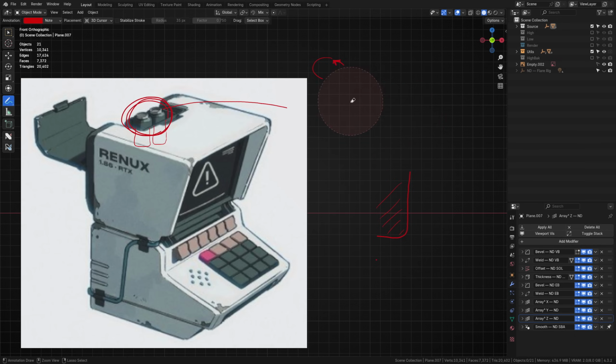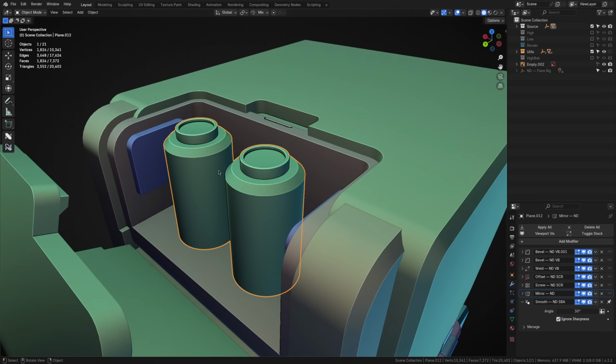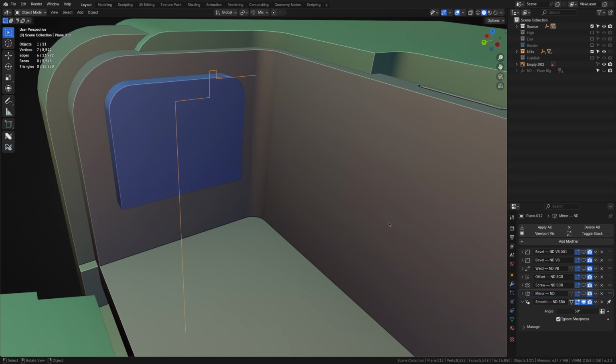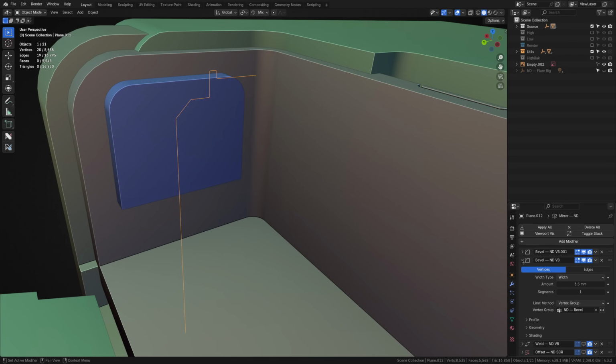Let's go over and take a look. I'll turn off all the modifiers. Here's the base sketch I went with. Now, I also used a couple of vertex bevels to curve the piece that sticks up at the top. I then also added a chamfer to this outside corner. I added it as a chamfer and not directly to the sketch because this allows me to adjust this detail later by tweaking the values in the modifier stack without having to manually move vertices around, which would be slightly annoying if I tried to maintain that perfect 45-degree cut.